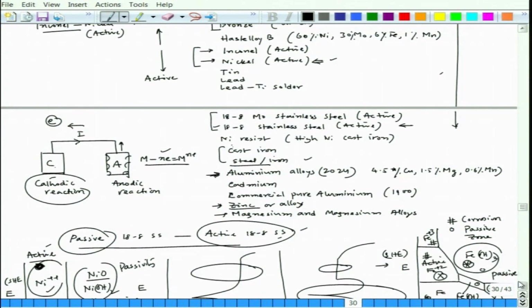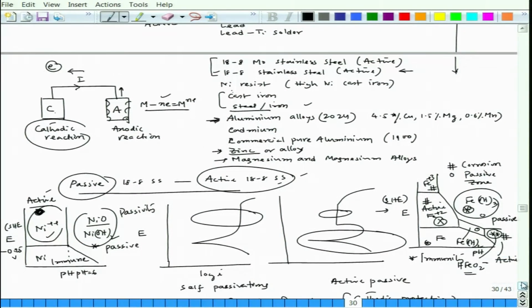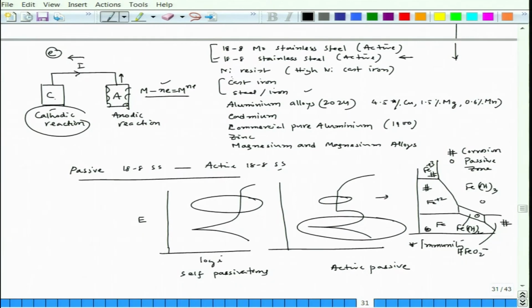Okay. So, that is the explanation for the correlation between active and passive, what is written in the bracket in that galvanic series we have shown. Passive means a passive layer has already formed, and active means it is not passive. It could be possible that some part in the operation gives conditions for passivation and some part does not. Then there could be huge corrosion in the same alloy, but one is passive, another is active, and the active component will corrode, fine.